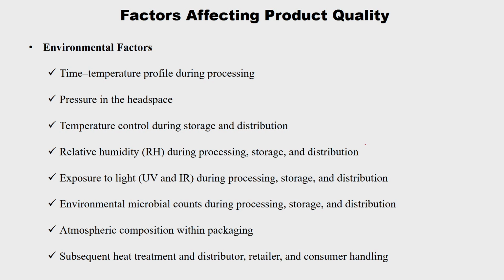So, based on this we have certain conditions, for example frozen condition. The frozen is minus 18 degrees centigrade. So, this is something under 100% relative humidity, and the second one we call a chilled condition. Alright, the storage condition, the chilled comes under like 0 to 5 degrees or sometimes 8 degrees as well. So, the relative humidity is also very high.